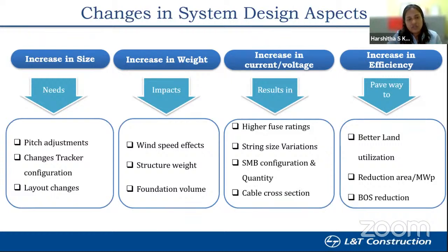Similarly, the increase in weight needs to be analyzed with respect to the wind speed of that particular location. So the site-specific wind speed and other soil-related studies which are done also have to be reanalyzed with respect to these LFM modules and the associated tracker. It can also impact the structure weight and finally the foundation volume, as I explained in the earlier slide.